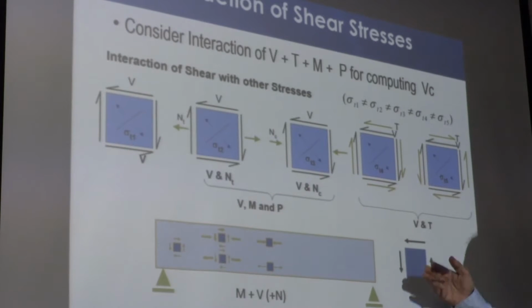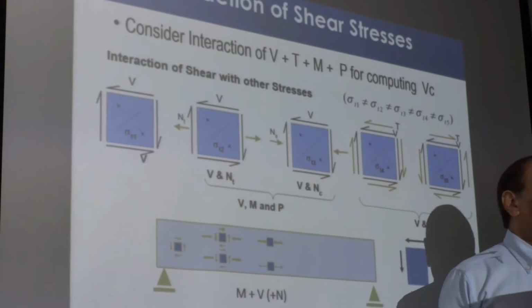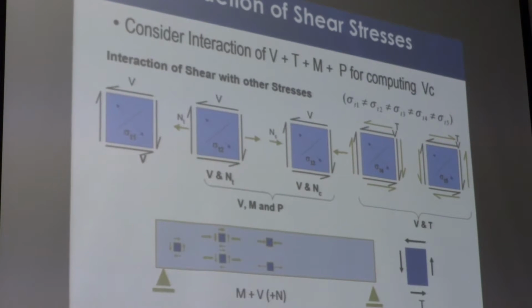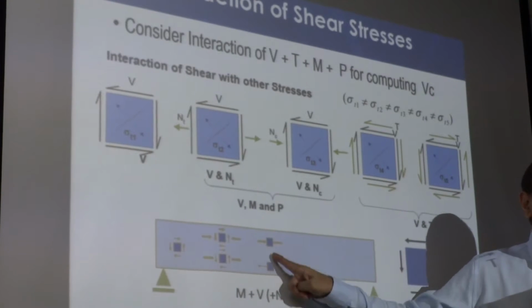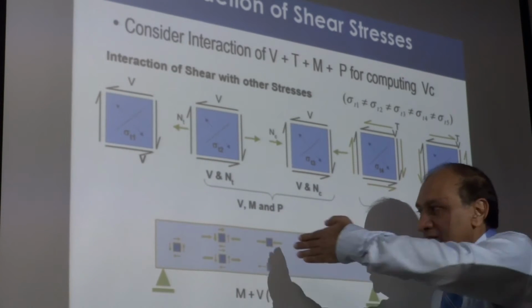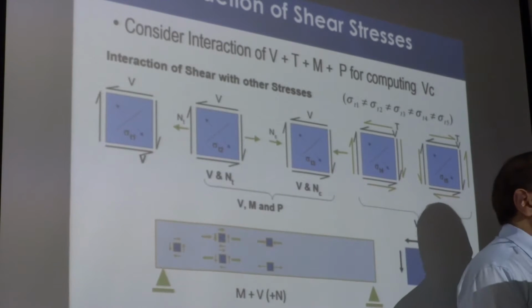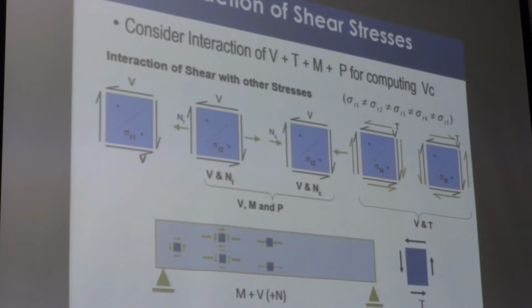Then let's say it's a column. You also have axial force coming from the outside. So add that axial force to this one, subtract from this one. So we have another issue coming. Then we have a shear going this way. This is only one directional shear. We have two directional shear. So we have two directions of shear interacting with each other. We have torsion also coming in. We have axial force also coming in. We have two bending moments coming in and warping coming in, changing all of the stresses and strains in the whole section. The core section is really in trouble, right?